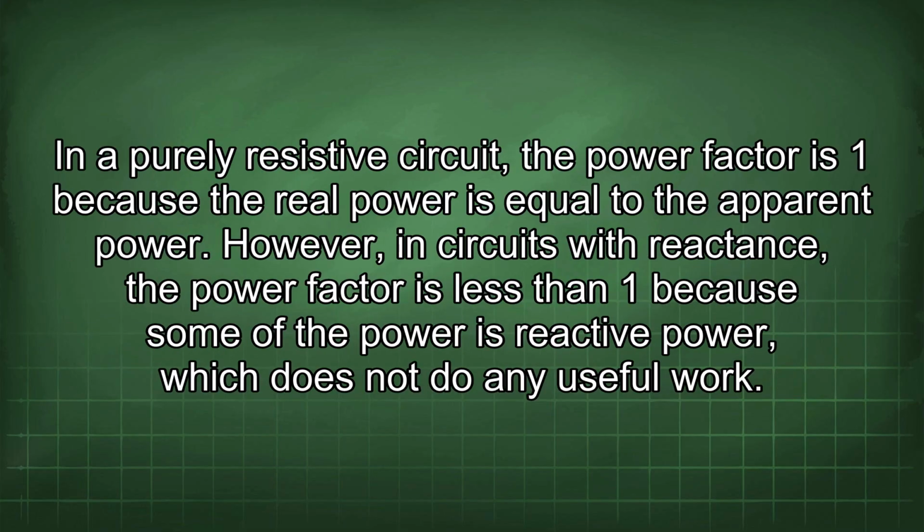In a purely resistive circuit, the power factor is 1 because the real power is equal to the apparent power. However, in circuits with reactance, the power factor is less than 1 because some of the power is reactive power, which does not do any useful work.